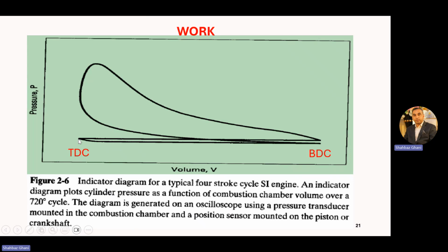Now at TDC, your piston is at TDC. The piston is moving towards BDC, and your intake stroke starts. From this TDC, it is going downward, like here in this line. When it reaches BDC, your intake stroke finishes.